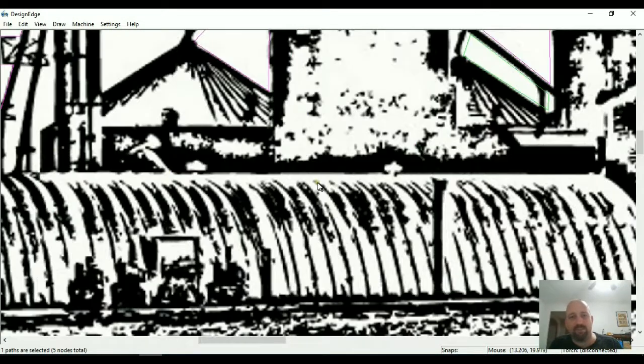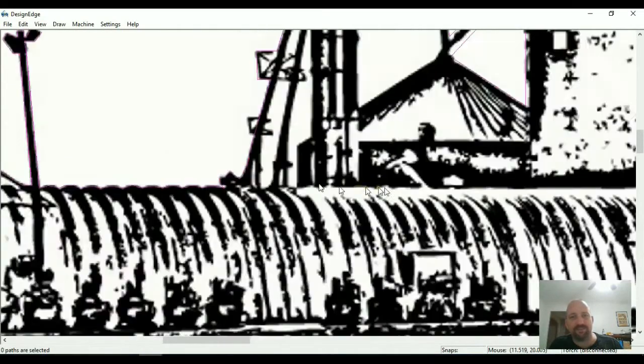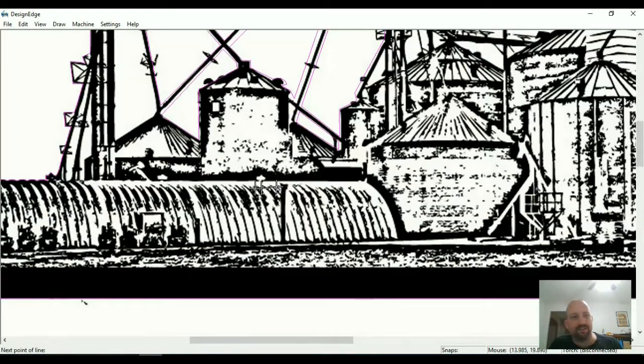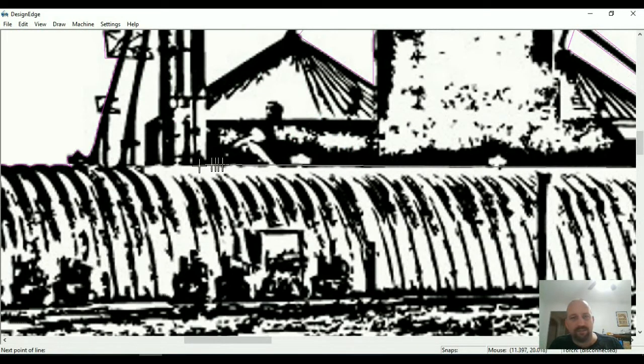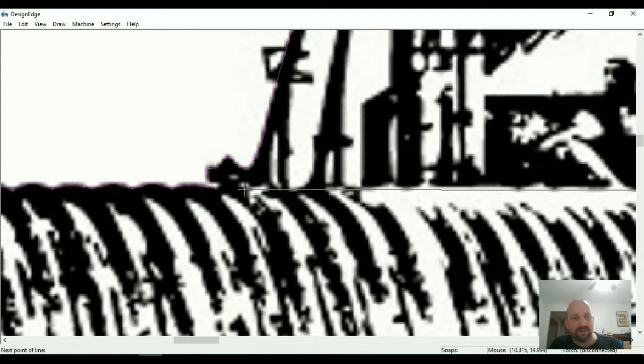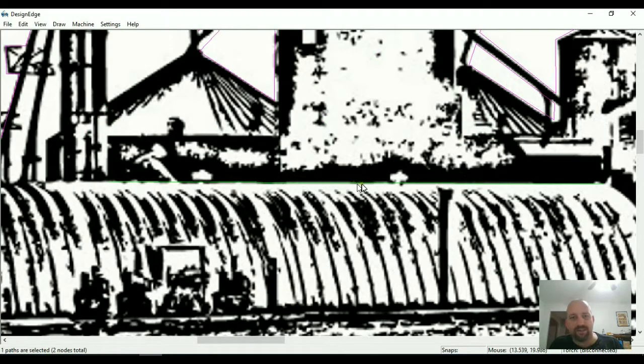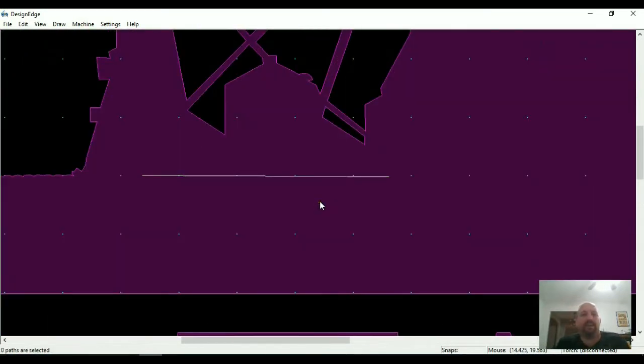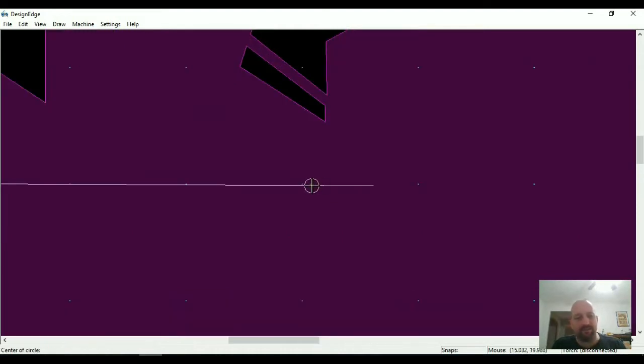Together. Now then, let's see, our Quonset Hut, as it goes, we're kind of losing some of that detail in there. I'm going to draw this across like that, and then to make that into a cut piece, what I'm going to do is Q for a circle, and I'm going to make that a 1/8 inch cutout.